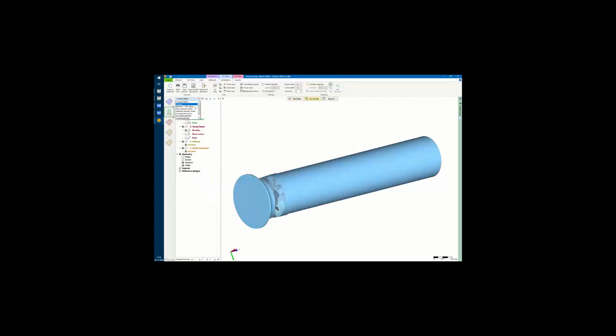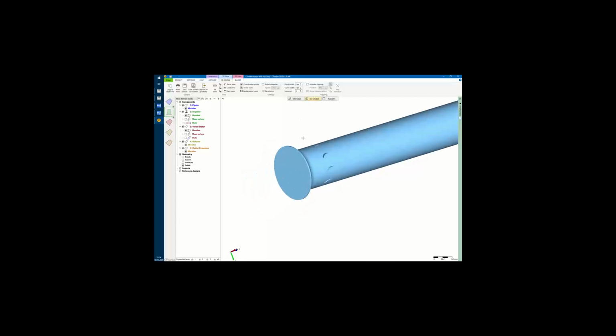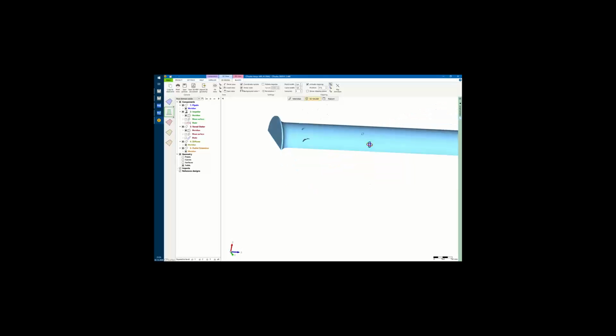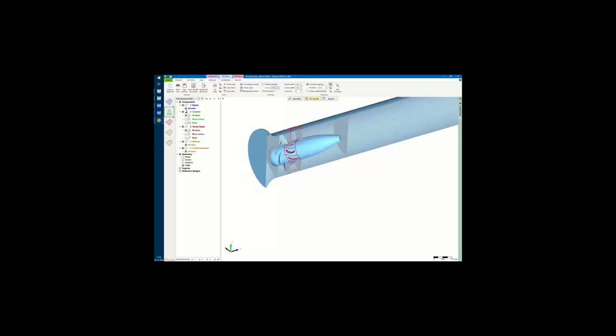All right, so yeah, this is the fluid domain that is going to be meshed, except of course for the blade passages, because we use TurboGrid, and TurboGrid does not operate with fluid domains. It's more some sort of curve-based format. But of course I could activate clipping, and maybe we would see how it looks inside. Yeah, so these are the fluid domains.